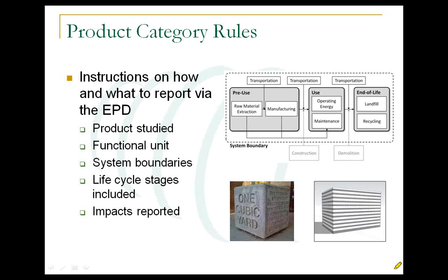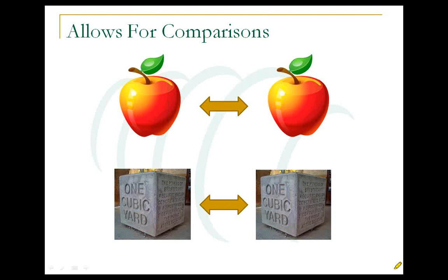It also sets the system boundaries, what life cycle stages are included in the life cycle assessment, and what impacts are being reported in the EPD. What it does is it allows for comparisons of one product to another, apples to apples, concrete to concrete, wood to wood. And the whole idea of life cycle assessment was really developed as a way